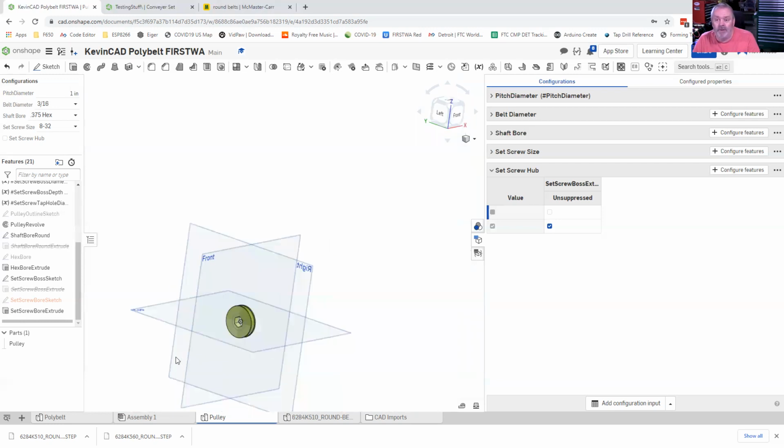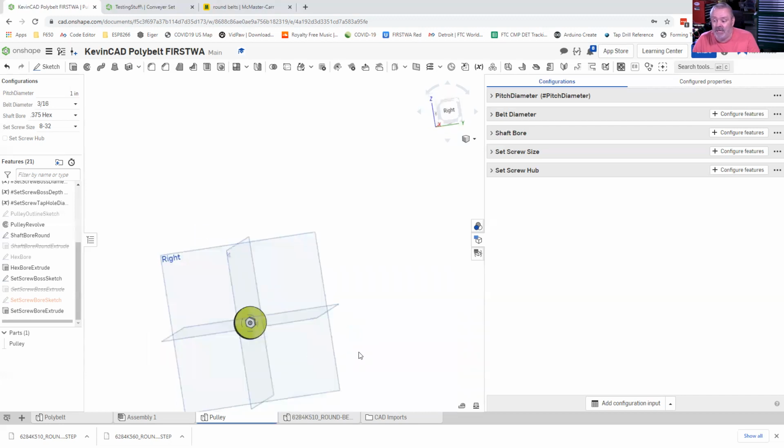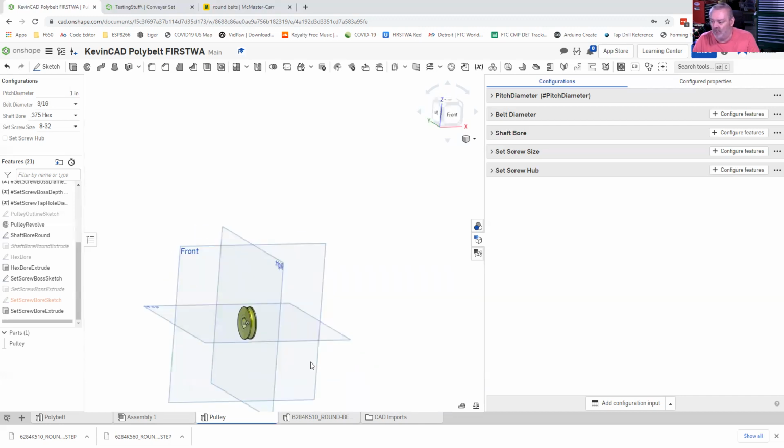Oh, hey, so one other thing, when you're 3D printing, did you know that 3D printers are not accurate? And that you occasionally need to change the bore, especially on round holes. I had forgotten all about that.